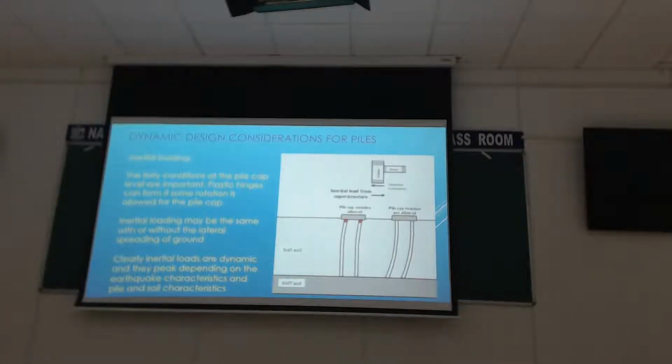Because if my soil is very strong and won't let this bending to happen, then the failure will come somewhere else. Yeah. So obviously the soil strength has a big role to play. Here we are assuming the piles are going through soft soil and into stiff soil. But imagine it's the other way around. Then it will be different as well.